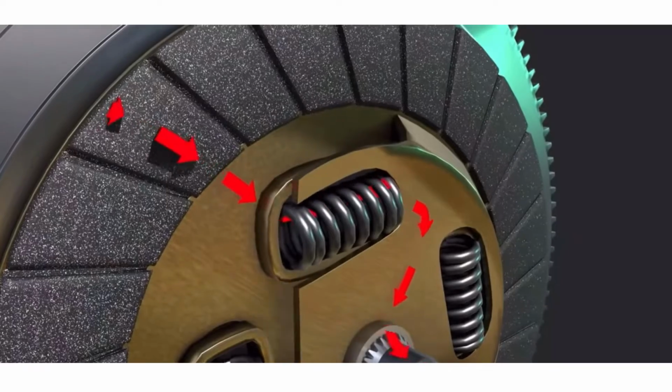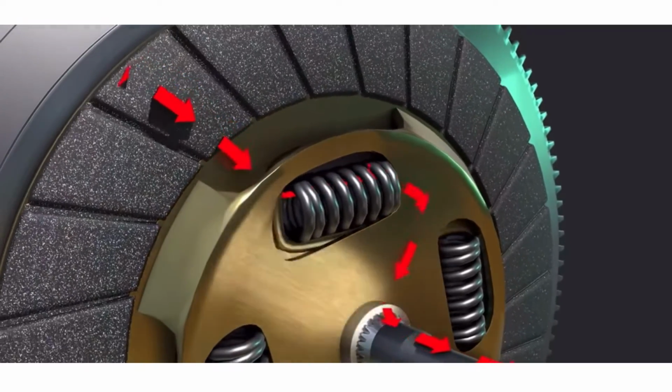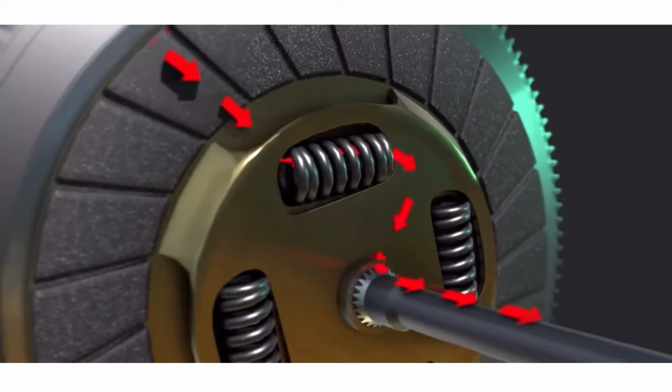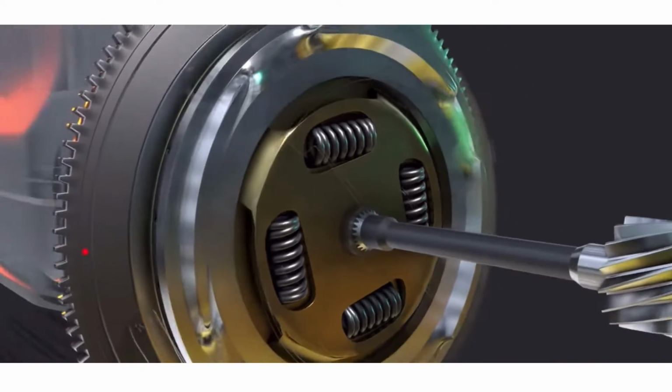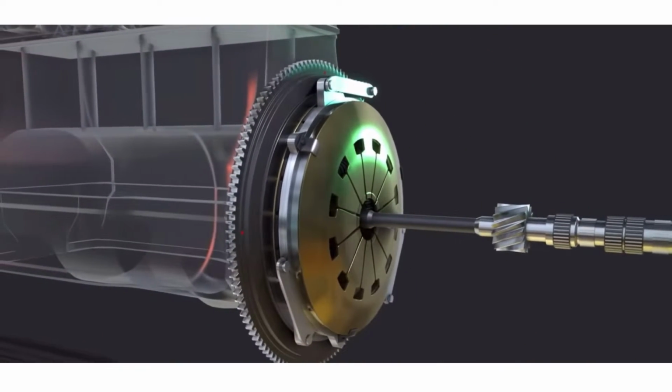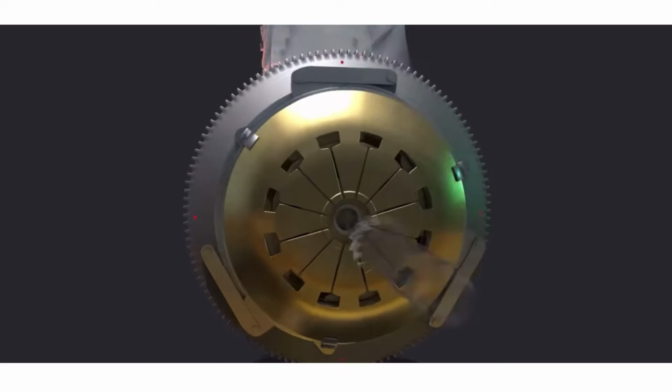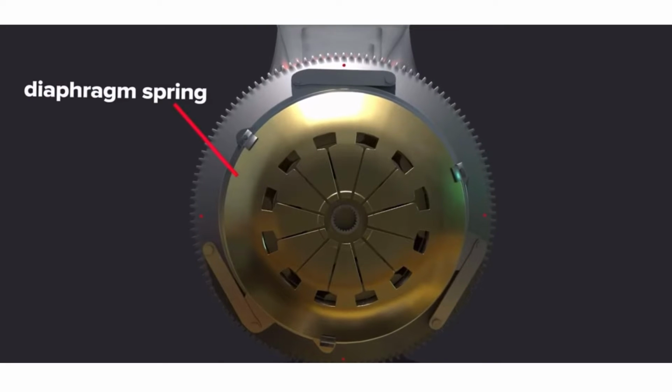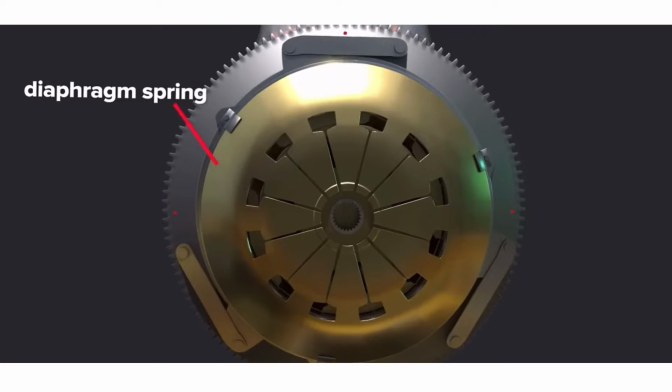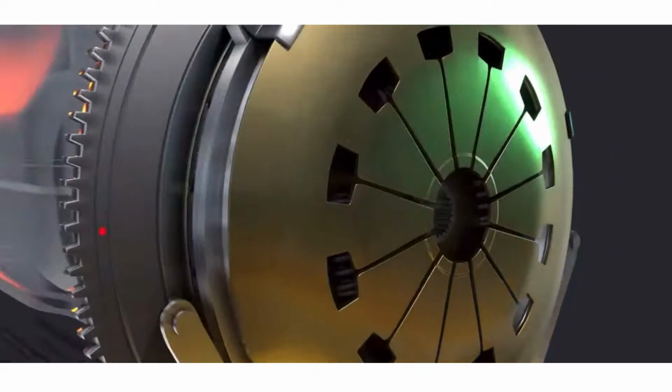6. Synchronizers. These are located between the gears and the collar and allow for the collar to engage the gear even if there is a speed differential between the two. Essentially, this aids in matching the speed of the gear and the collar.